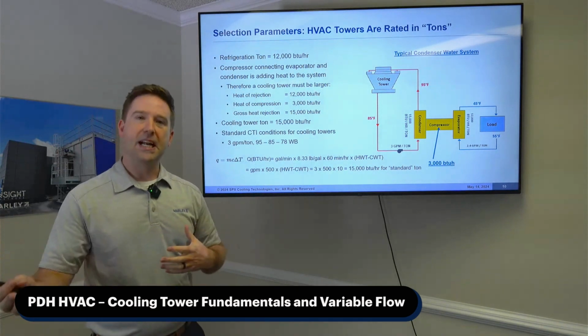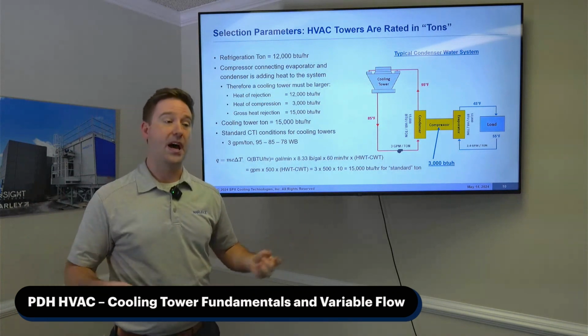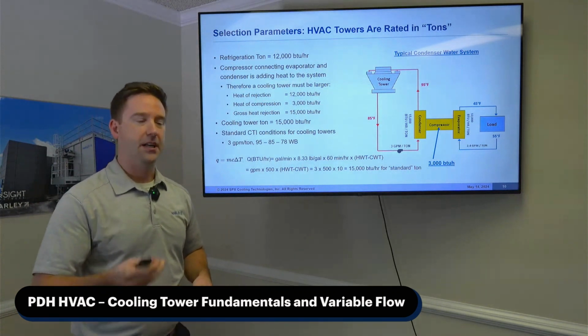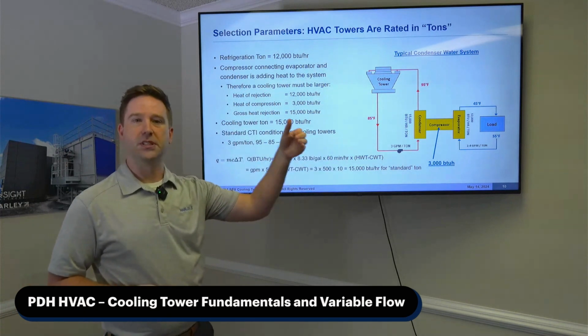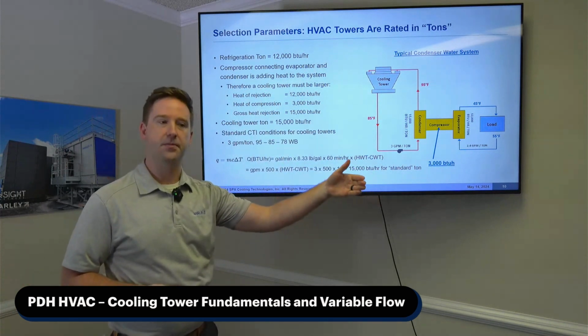So, as you're designing your system, say maybe you have a 500-ton chiller and you want someone to design for it, you've got to understand that the tower is actually going to see a larger heat load than that 500 tons.